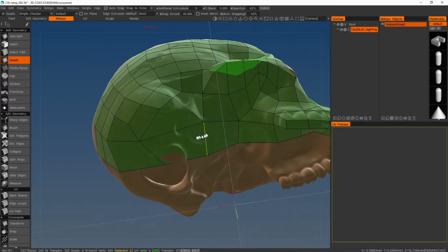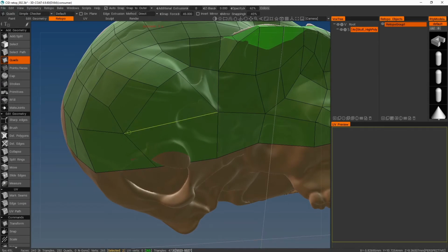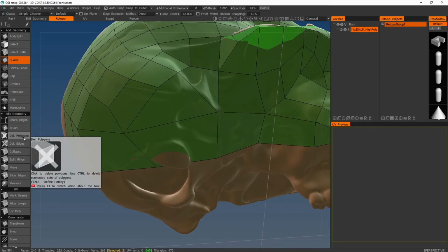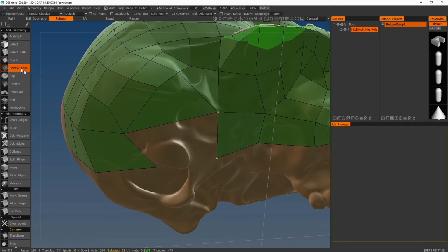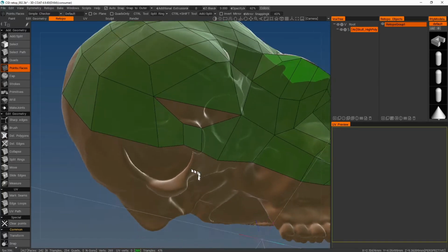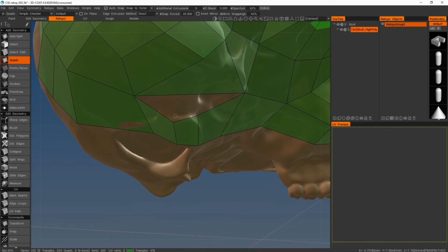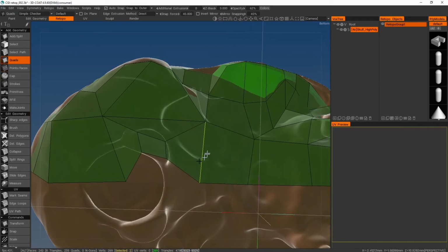So here is a typical problem where I've failed to provide enough triangle resolution and it hasn't captured one of the significant details of the skull. To fix this problem, what I do is I delete the polygon and then I'm going to add a new quad on the feature, and then I'm just going to build around to create new quads.